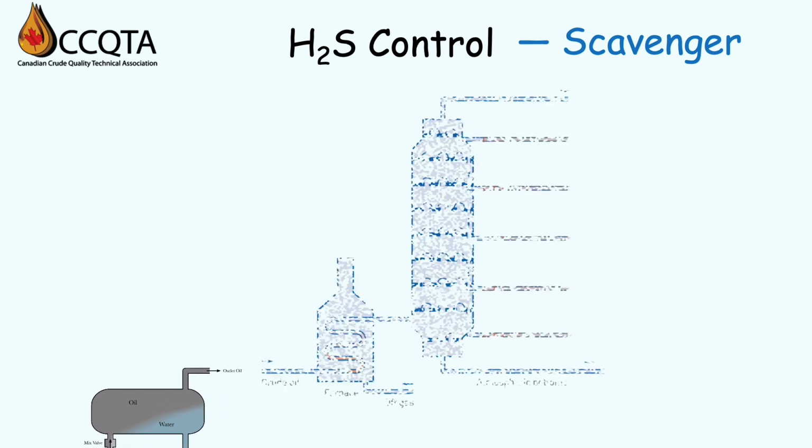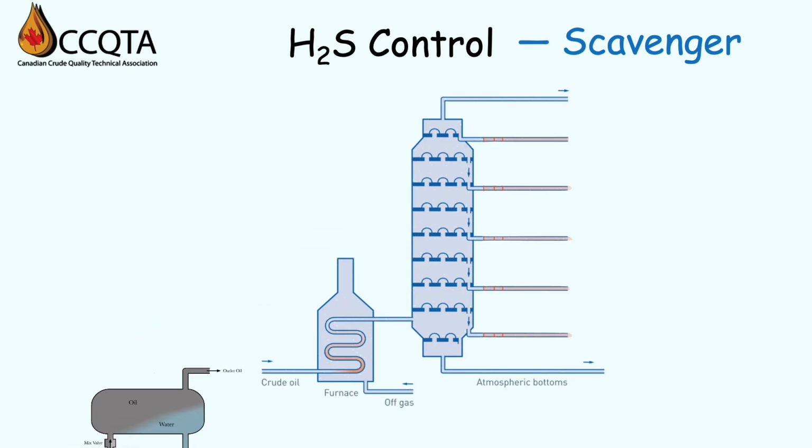In the atmospheric crude tower, available salt can hydrolyze and form hydrochloric acid, which travels into the crude tower overhead system. When HCl contacts MEA, a liquid amine salt is formed. This very corrosive salt results in corrosion to trays, heat exchangers, and piping in the overhead circuits. The resulting corrosion is very costly and in many cases requires the refinery to shut down for repair. Methylamine, on the other hand, forms a less corrosive salt, so MMA triazine is favored over MEA triazine.